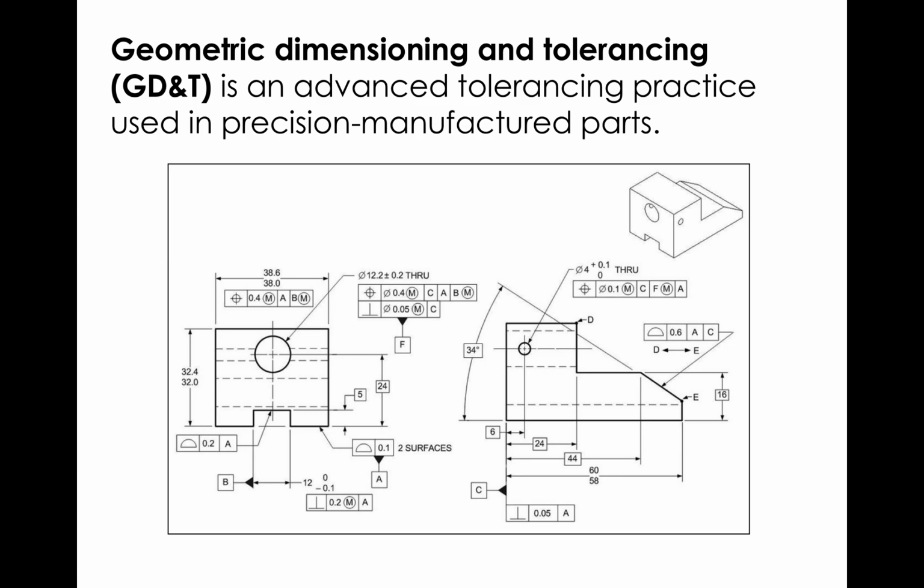So we have dealt with standard tolerancing thus far, tolerancing to achieve a particular engineering fit, right? That has to do with holding basically one dimension, or maybe two dimensions, within a specific range. GD&T covers holding actual shapes to a certain shape. So how circular is your circle, let's say? How square is your square? How flat is your line? How perpendicular are two lines to each other? So that's basically what these designations mean.